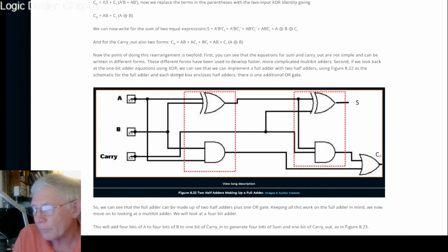All right. So what about a 4-bit adder? Oh, and here's what the circuit looks like for a full adder. 2 exclusive OR gates, 2 AND gates, and an OR gate. It's pretty complicated. It's not as trivial as we'd like it to be. And there's potential for a 3-gate delay going through this network. The way it's implemented here, it could be implemented differently and in a 2-layer, but the way it's typically implemented, we get 3 layers.